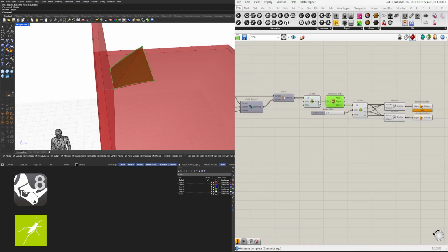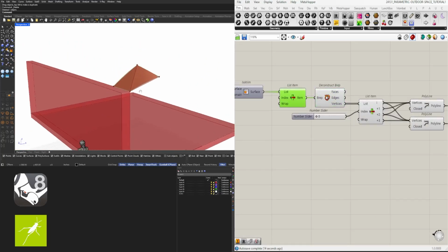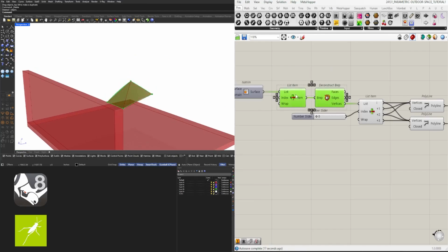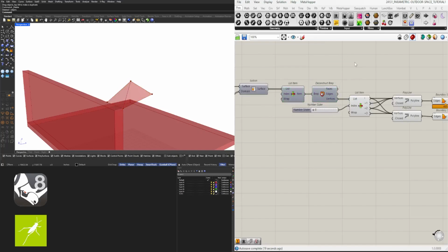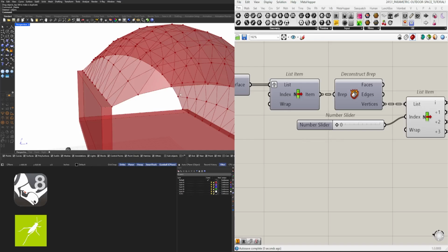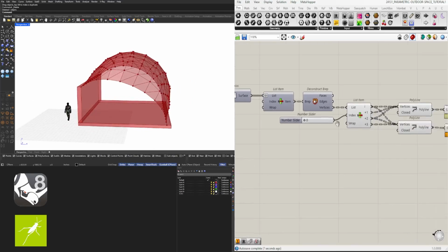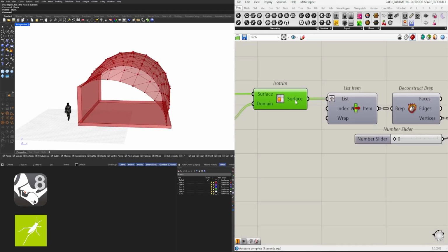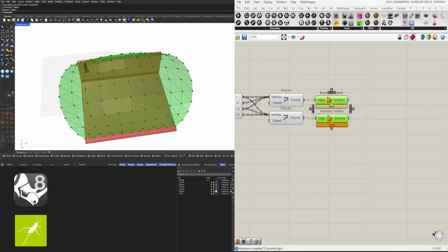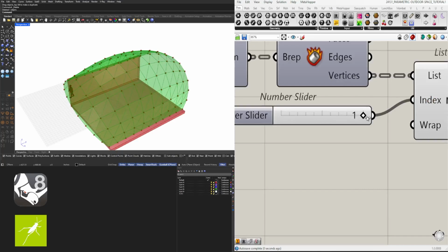And now what I'll do is I'll hide. Well, first, just know that since we did it to one panel, we can technically do it to all of them at once. So I'll take this and this, hide the input, and then I'll go here to list, and then I'll go to graft. So now we've basically redeveloped this surface into these triangles. And we can change the direction that they are located or that they are divided.